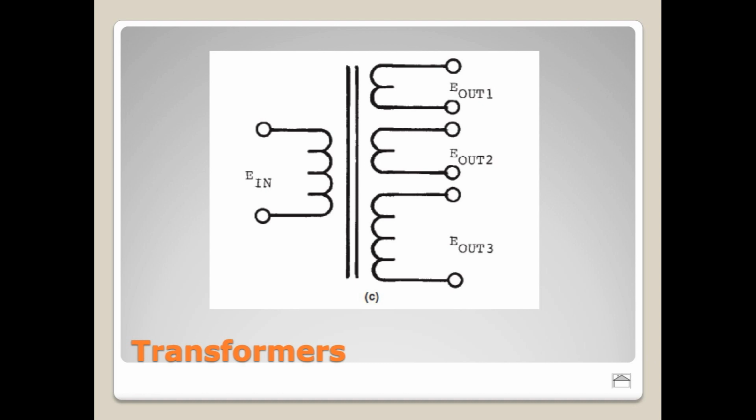We talk a good bit about the power supply in here because that's a very basic troubleshooting technique, and it's not a very difficult circuit to understand once you understand how all the components work. One of the most common complaints is, my piece of equipment just won't turn on. Well, if it won't turn on, where do you think the problem might be? Right, the problem's going to be in your power supply somewhere, somehow. Sometimes my lights are flickering, right? Oh, okay, well, maybe you've got some failing capacitors in the power supply, right? I mean, it's a very common thing to have to troubleshoot power supplies.